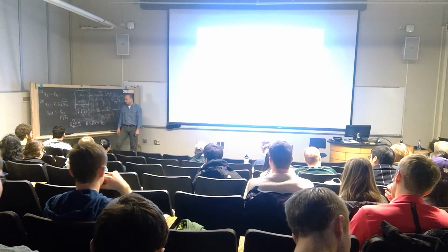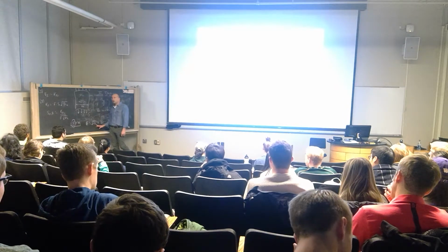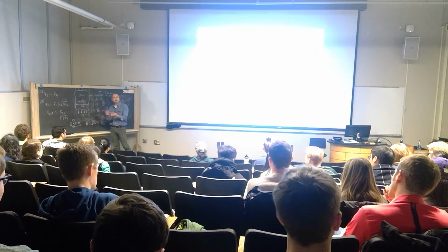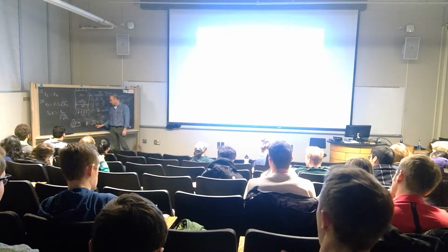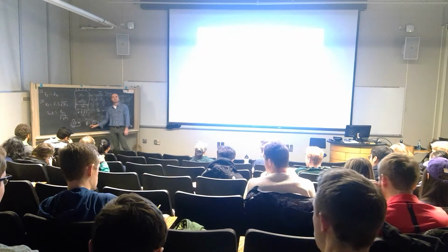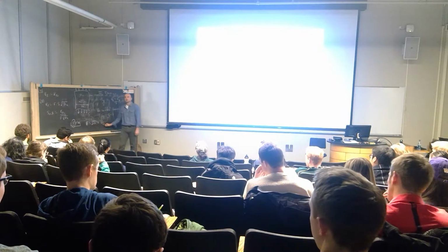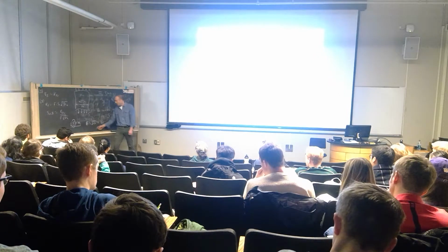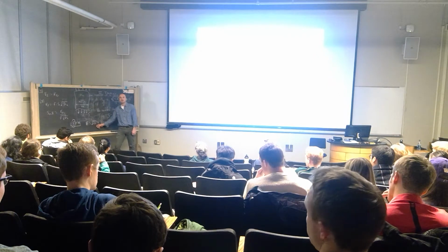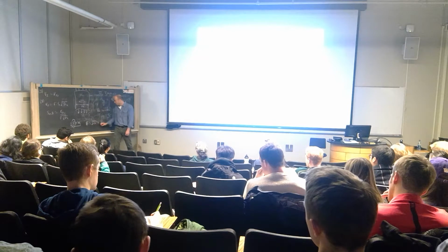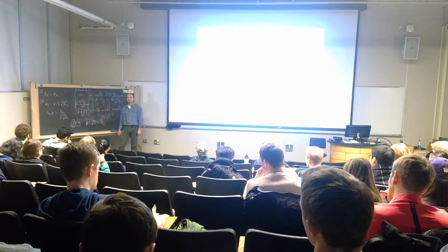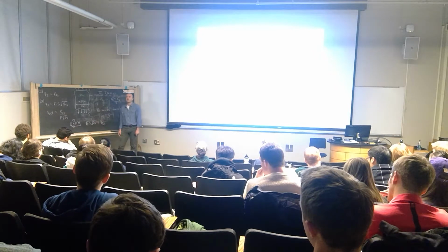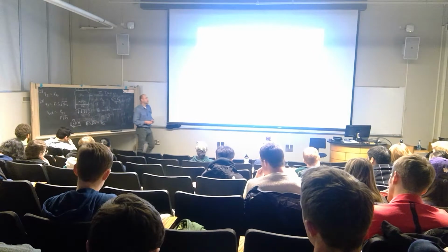And then the other thing I do is, let's say, for example, I don't have the flaw length because the contact characteristics obscure the crack and the transition between fatigue and non-fatigue. I know what the stress is, and I know what the fracture toughness should be, right? I can go back and check what the flaw length is, and then for that flaw length, I try to check again to see if I can understand what the fracture toughness is. So there's many things I can do here as a failure analysis expert.